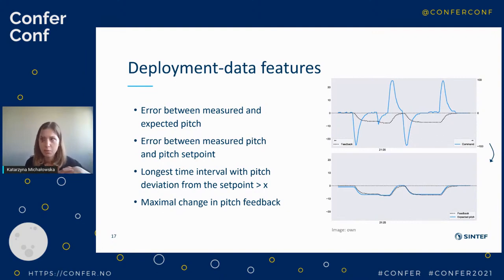We did that using a simple linear regression, which was good enough for the model to work. And then we compared this expected feedback, or expected pitch, with the measured pitch. If the deviation was larger than minimal, that would indicate that there is some problem.